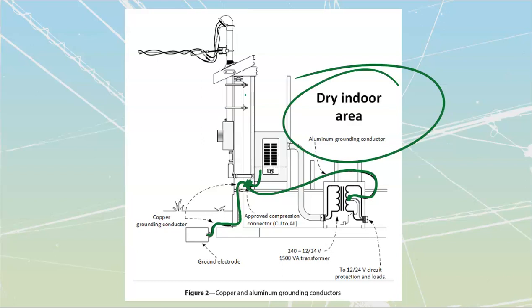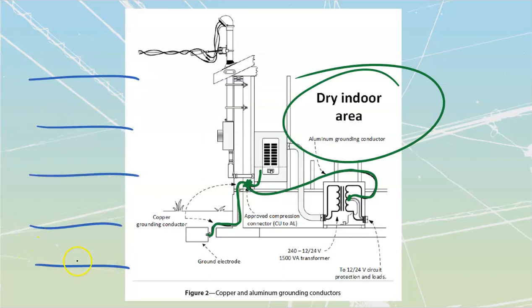Now, we will have some times where we might have multiple single-phase transformers that are going to be fed inside of multi-family residential, right? Where we've got apartment buildings and we're going to take high voltage to each floor, then we drop to a transformer and sub-distribute, so we don't have to go as far with our high amperage cables. That's a very common place where I'm going to have multiple grounding conductors that are all going to get carried down, from floor to floor to floor to floor to floor, all the way down to your main service inside of the bottom level usually. That is then going to have the actual grounding conductor. And so you're going to have these aluminum conductors that are going to go from floor to floor.